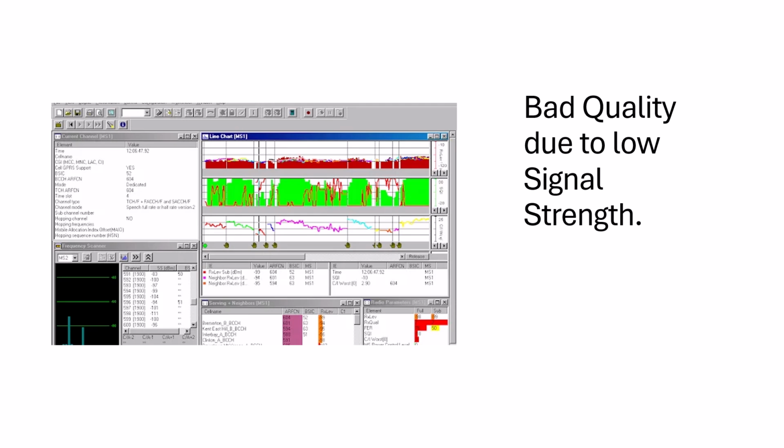High-rise buildings can cause reflection, diffraction, or blocking of signal, further reducing effective coverage. Poor cell selection or overshooting. Overshooting cells that serve users who are actually farther away from optimum can lead to poor signal strength on the user side. If the network parameters such as neighbor list or handover margin are not optimized, a mobile may stay in a distant cell instead of handing over to a closer one, causing low signal strength.